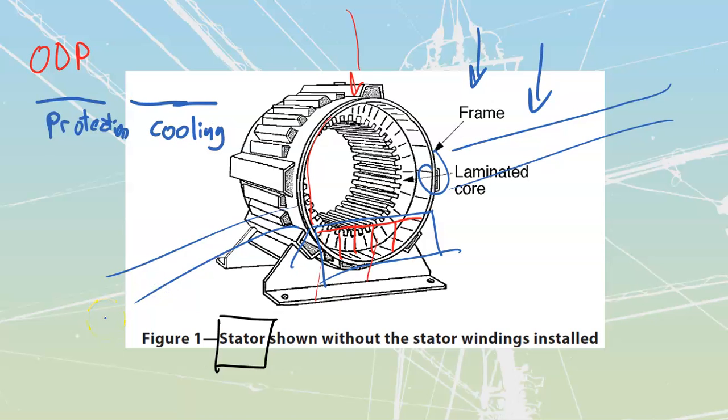It's not going to be as common for us to pipe stuff in as it is for us to close our machine. We're going to talk about another common designation over here. The first one is the TENV, totally enclosed, non-ventilated. We have no external types of ventilation that this thing is going to have. TENVs are going to be a completely sealed unit. We use them pretty much in any type of application.